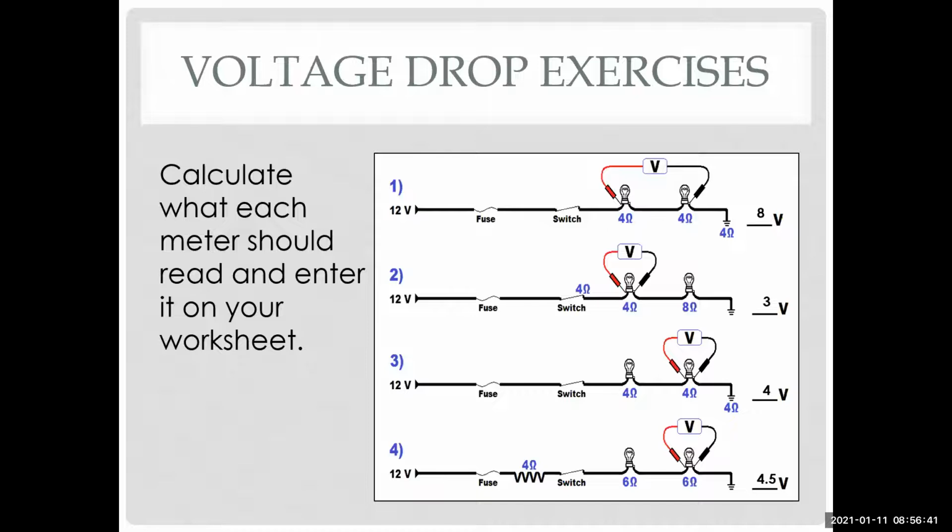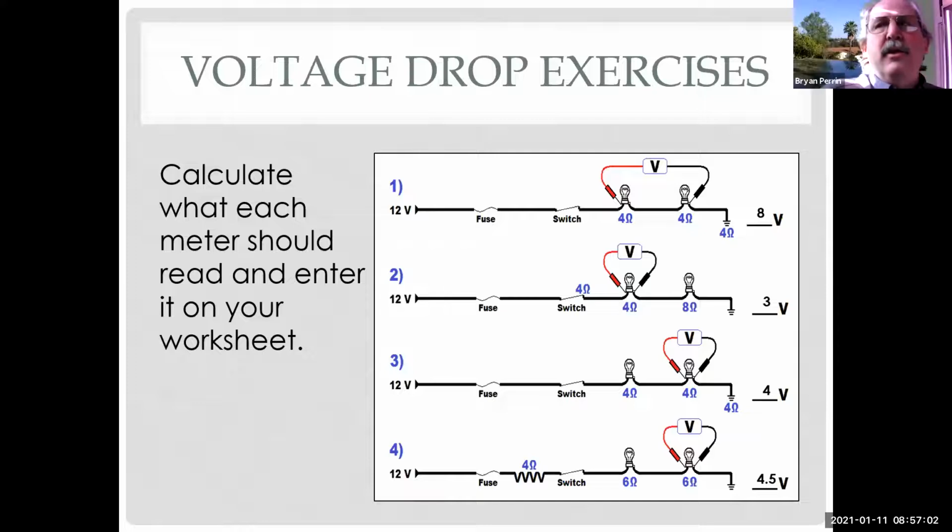Now this kind of confuses me. I might have the numbers wrong. If I was testing a negative cable from the battery post to the ground that it's connected to, with a multimeter, I should have 0, right? While the engine's cranking, ideally you would have 0. You're allowed 0.2 volts or 200 millivolts.